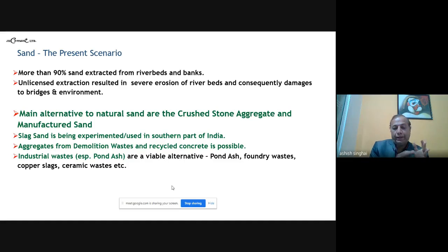Because in the entire concrete, cement is almost 12 to 15%, and almost 75 to 80% is constituted by aggregates, coarse aggregate plus fine aggregate. So the coarse aggregate and fine aggregate in totality, about 70 to 75%, now belong to the same family. So the larger chunk of your concrete mix now belongs to the same family. Hence, the cohesivity, the strength and the workability are far more than a river sand produced concrete.